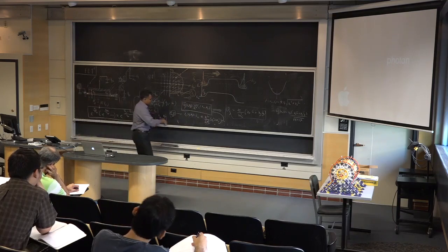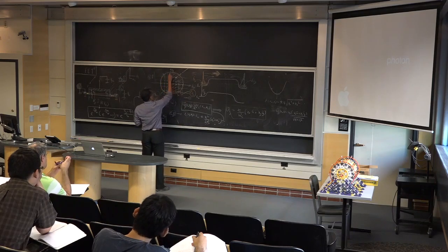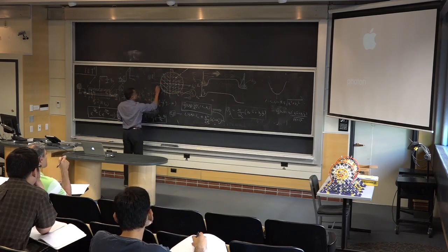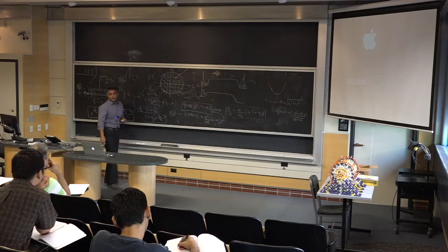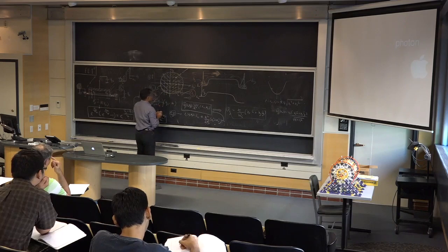Similarly, the left-going carriers, I think you can see now, hopefully the argument, are filled by the drain, and therefore they have a characteristic Fermi level, which is the Fermi level of the drain. And see the picture: there are not just carriers moving purely to the right.